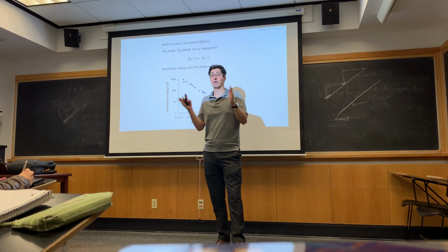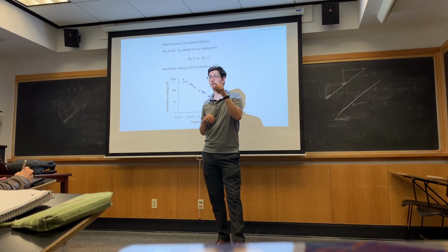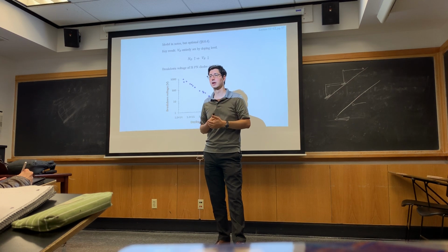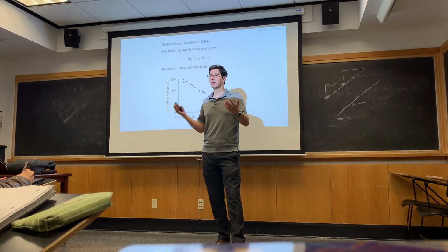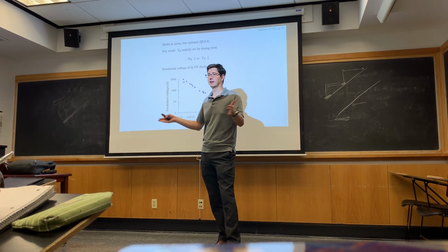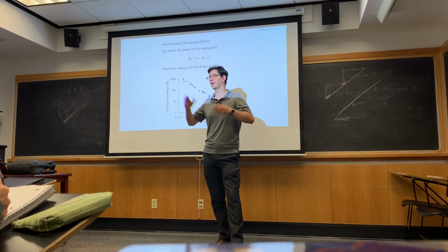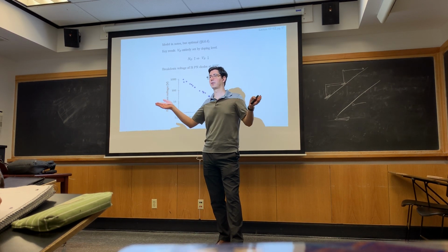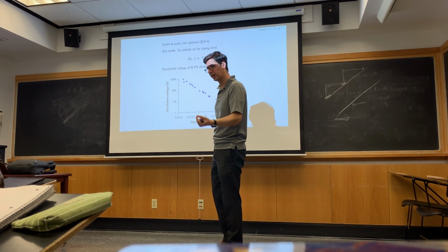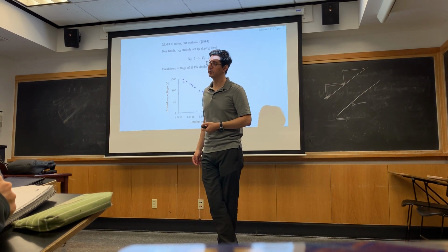But the depletion width is very, very different, right? The depletion width, I think, goes as the square root of the doping if it's the lightly doped side. So if your doping changes by 100x, your depletion width changes by 10x. That's going to really reduce your electric field. You have to drop the same voltage across 10 times longer, so your electric field's going to go down. But what you're saying is not completely wrong. I'd have to think about that a little bit more.